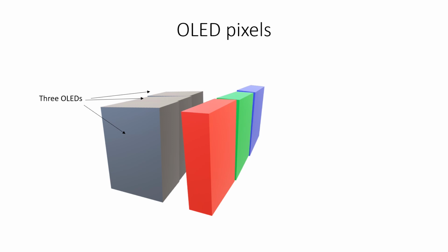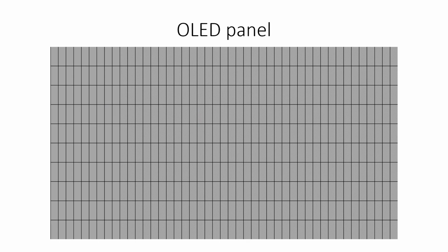where the OLED is off, to white, where each OLED is on. Then by varying the current through each OLED, the pixel can be made to be any colour. The dimensions of each pixel are approximately 0.3 mm square. A matrix of OLEDs can then be made into a panel with 3 OLEDs per pixel.